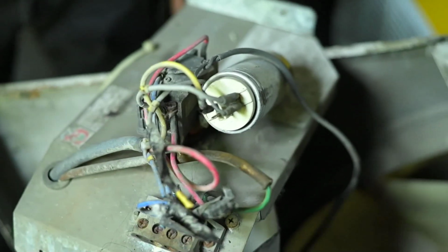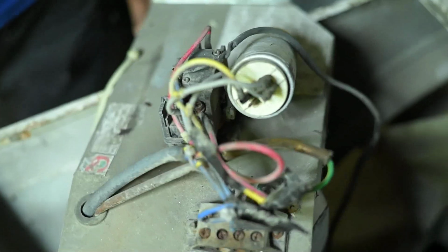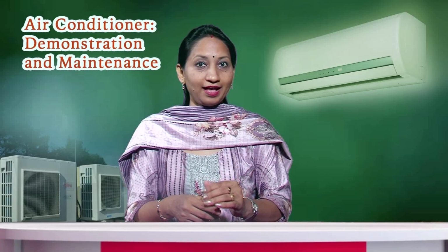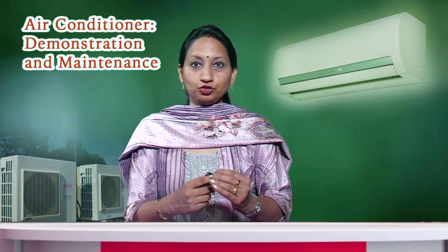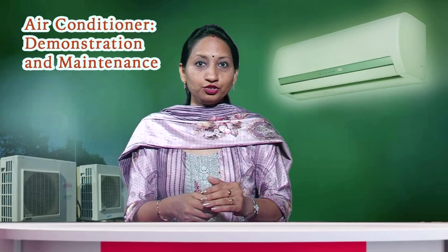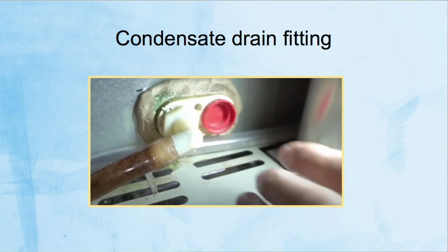The condenser unit located outdoors is positioned in a location where it can expel heat efficiently and where air flow is not obstructed. It should be positioned level to ensure proper drainage of the condensate.